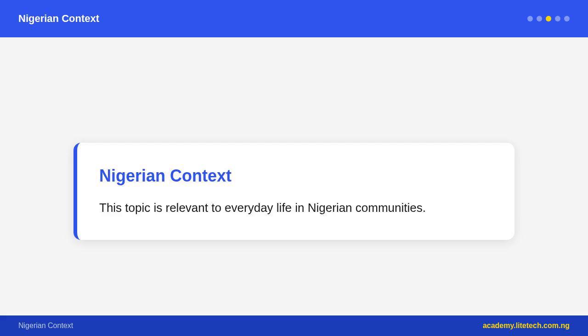Hardness is tested using standardized methods. The Brinell hardness test presses a hard steel ball into the surface of the material under a known force, then measures the size of the dent. The smaller the dent, the harder the material. The Rockwell hardness test uses a diamond cone or steel ball and measures the depth of penetration.